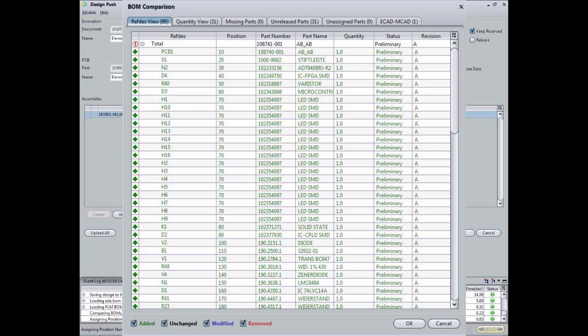Now a BOM comparison report is opened. The information on the different tabs is highlighted with different colors. The first tab contains an overview of the different assembly positions. In this case, all lines are green, because we are transferring our data the first time. All elements are new. If the module will be executed again, the colors will change. The new color will depend on the status of each individual component. It could be that it is new, has been changed, has been deleted, or is just as it was before.